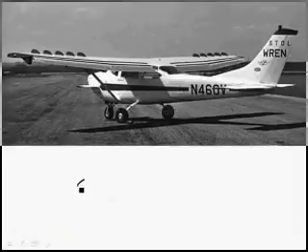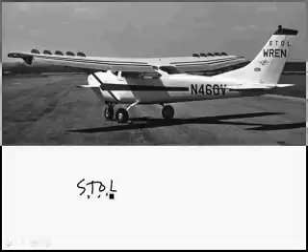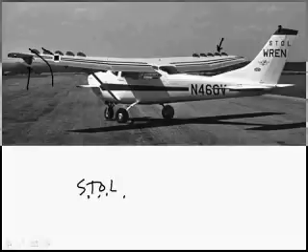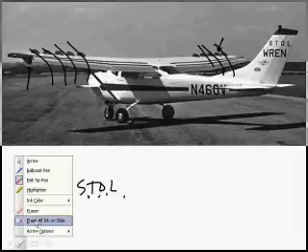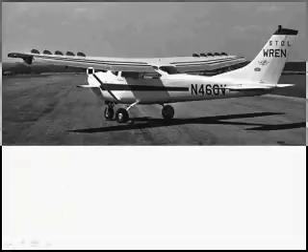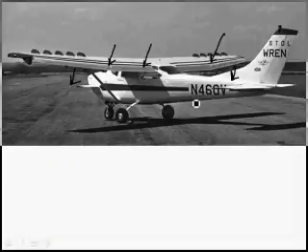And of course, here is a STOL. STOL stands for short takeoff and landing. And they've messed this airplane up good. They got some kind of funky wingtips going on. They've got wing fences, and of course the wing fences are going to keep the airflow going straight over the ailerons. It's hard to notice, but in this short takeoff and landing aircraft, the ailerons are actually going down, drooped ailerons, and it looks like, I can't tell for sure, but it looks like slotted flaps. Wow. And of course this airplane, I'll show you another picture shortly, it also has a canard. This is a really short takeoff and landing aircraft.